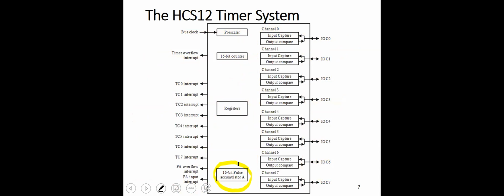Okay. So these input capture and output compare channels, their operation is associated with this counter, which is connected to this clock, because these are purely timing features, timing operations. So you need time, and to have time, you need your counter to be connected to some predefined clock. While this counter below can be connected to any event. So basically, it counts events. It's not connected to the e-clock. We will see where the input of this counter comes from.